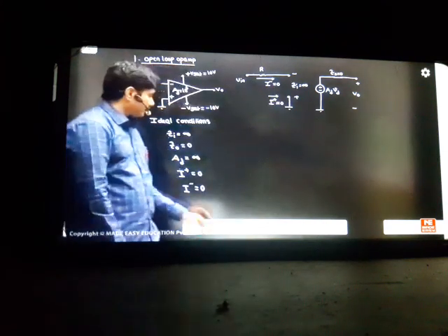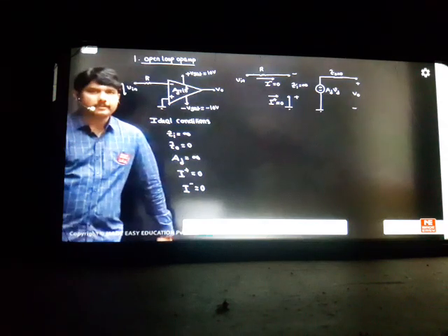So nicely I am showing your inside op-amp structure is like this. This is a voltage controlled voltage source diagram. Ideally you said input is infinite, output is 0 inside the device. There is one external R from outside. If you see the concept like this, you can easily understand the situation now. This is the negative sign, this is the positive sign. The current going here is I minus current, and the current going here is I plus current. Naturally I plus will be 0, naturally I minus will be 0, because no current will go into an open circuit. That is the meaning in the ideal condition. So I minus and I plus will be 0 always.